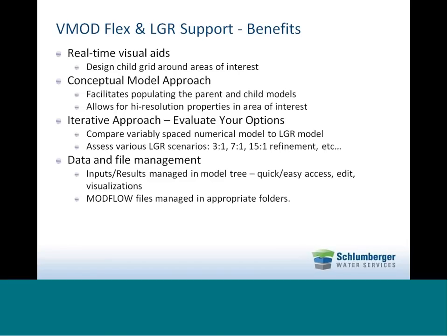In addition, if you're learning LGR and you're new to the capabilities, you can also assess various grid refinement scenarios. For example, you can try a child grid that has a 3-to-1 refinement aspect. With a few clicks, create the inputs, run the simulation, take a look at the heads to see if it's giving you the results that you want. If not, you can go back and generate a new LGR finite difference grid with a different child grid refinement aspect and generate another numerical model. So again, it's an iterative approach that allows you to compare several numerical models for your project-specific needs.